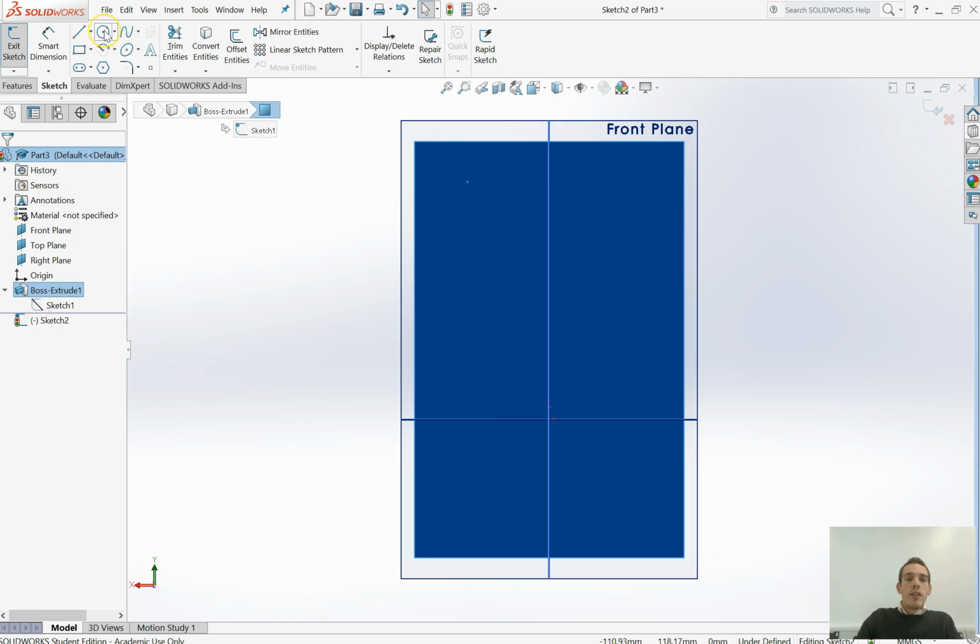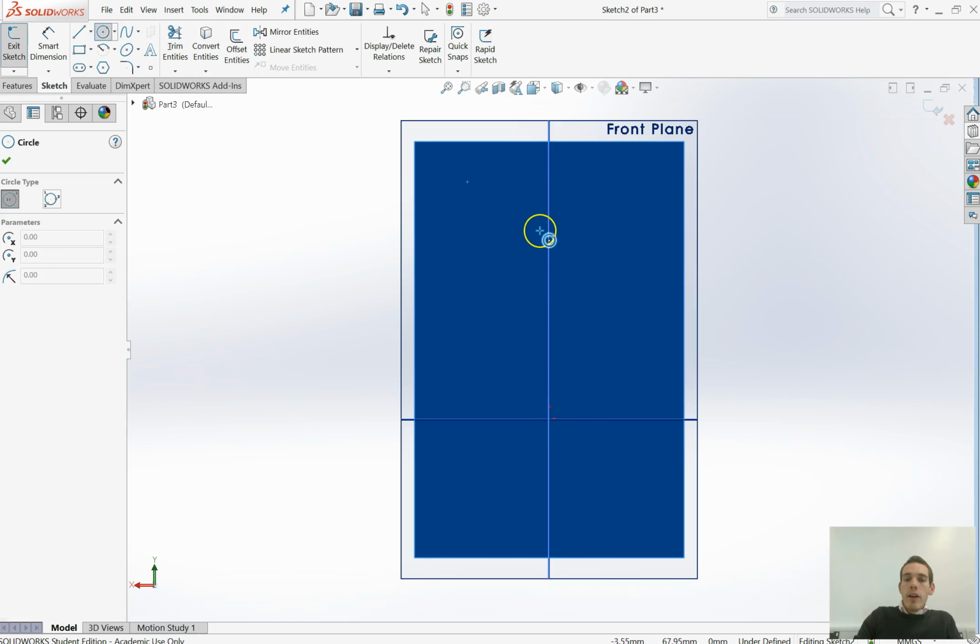Okay, so what I'm going to do is take two things actually. I'm going to take a circle. It's really good. You see that whenever you're creating a sketch, if you hover over a plane or something like that, it snaps to it. You can see it highlights that plane and effectively snaps to that plane. Now, we talked about relationships in terms of parent and child relationships with features. Sketches also have lots of relationships built into them, and we need to learn about those. I'll talk to you about those in more detail, things like tangency and concentric relationships. But we'll talk about those in a bit.